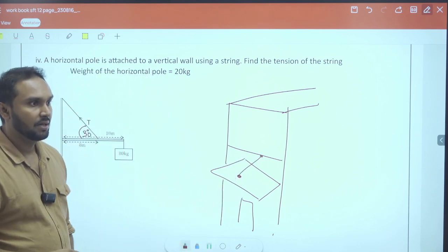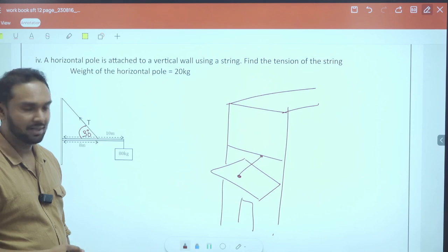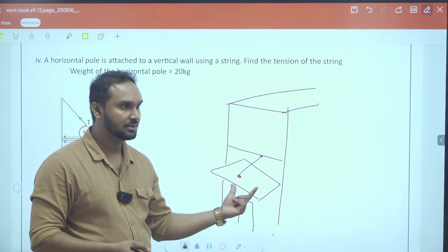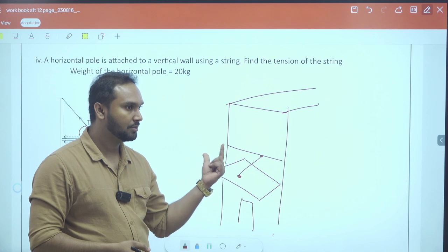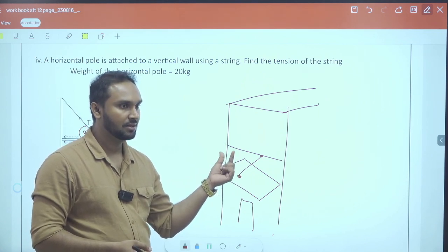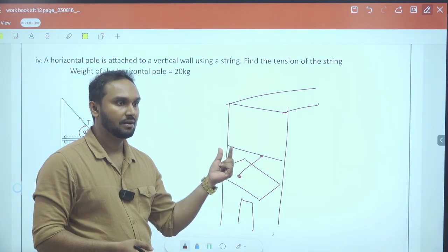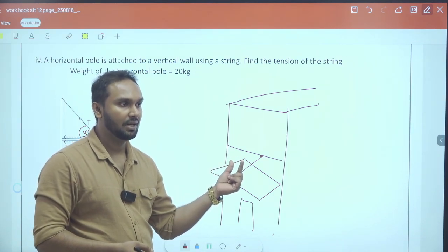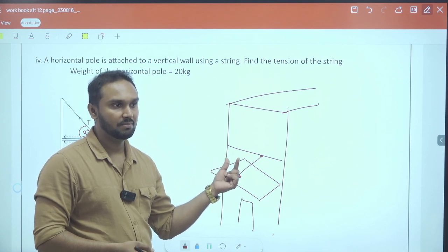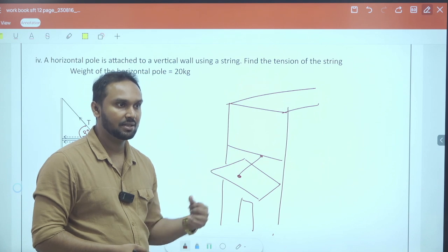Right? And now you are given this job. So you have to know the weight of the glass, and you have to know how much tension will come to the cable. And depending on that, you have to decide how much girth should be there in the cable, how much strength it can bear. You have to calculate and understand that. And depending on that, you have to select the cable.